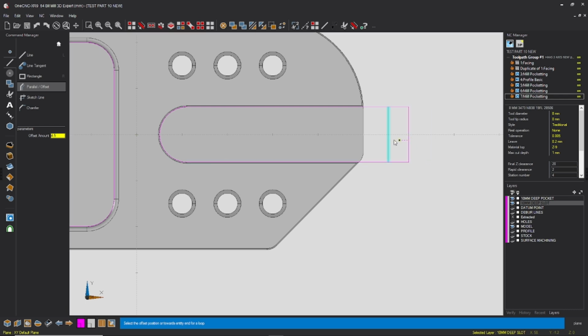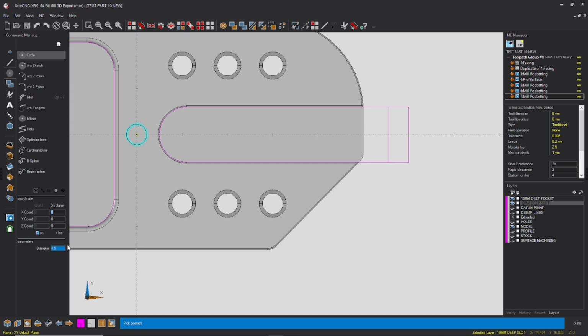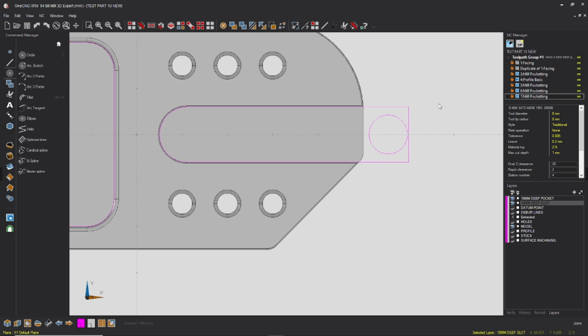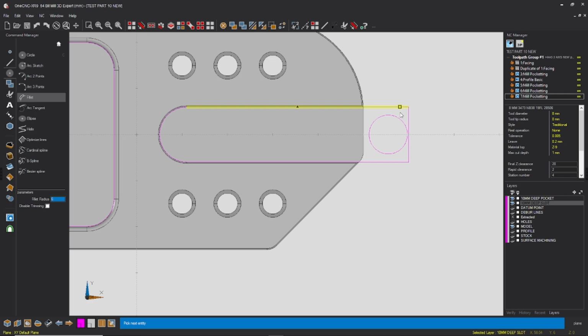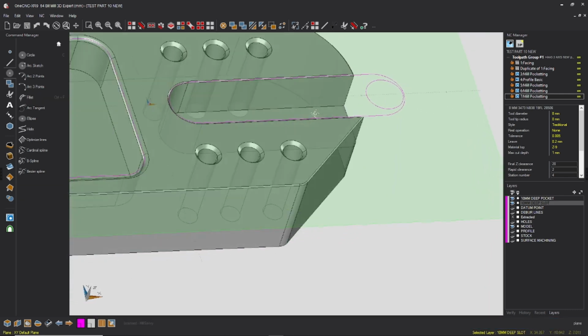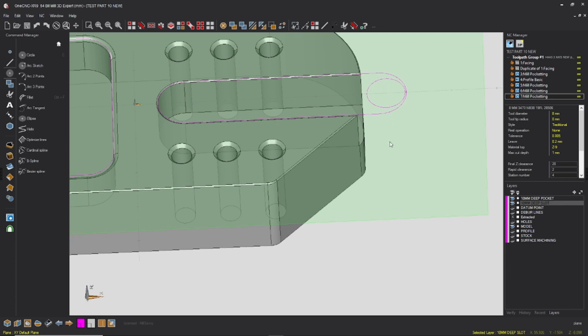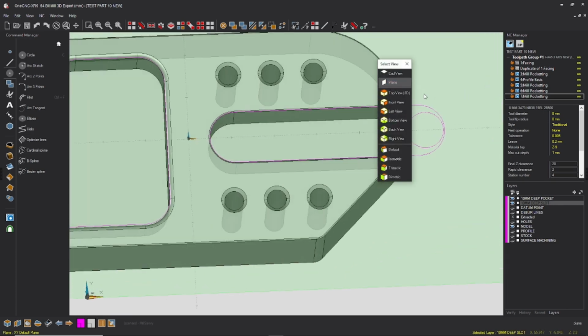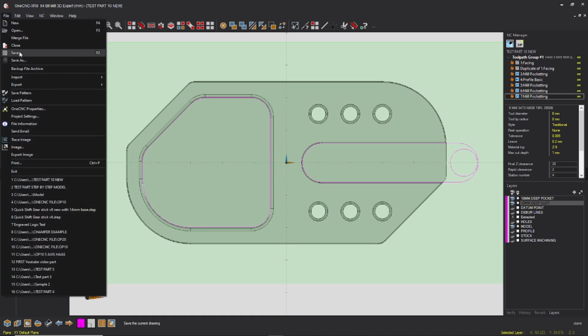I'm just going to put a circle in the middle of that, which is 8.5. Click it on there where it snaps to the center. Just grab that line and delete it. And then I'm going to use my fillet command and put some 6mm fillets on here. Right, so now we've got our slot, we've got our entrance point, which is safe to plunge down because there's nothing underneath it. Go back to our plane, another time to click save.